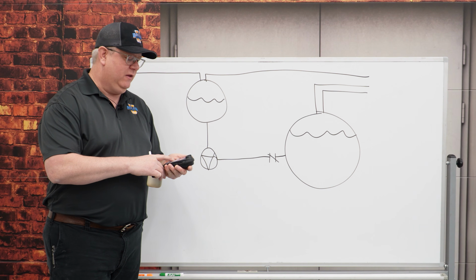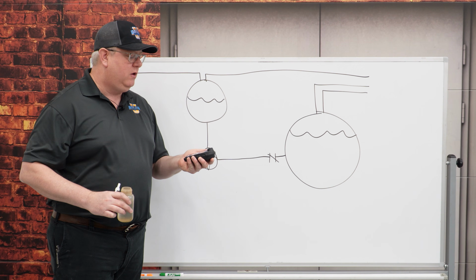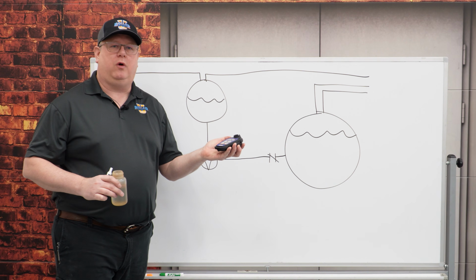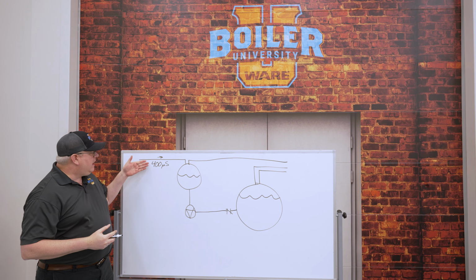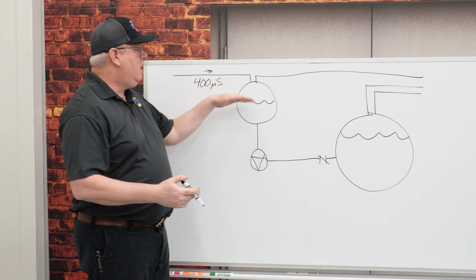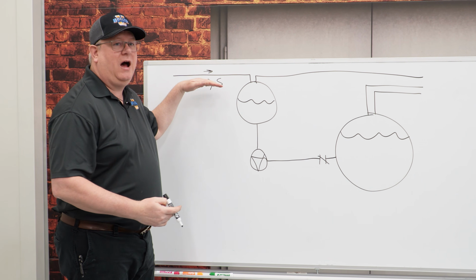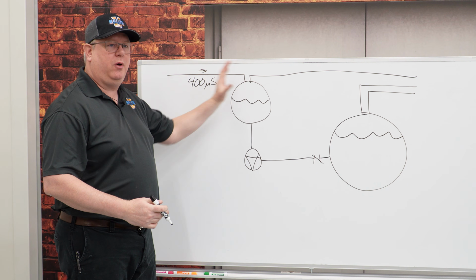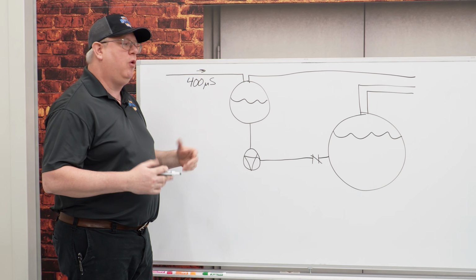And so if I read this freshwater sample out of our softener, conductivity is about 400. So if we've got incoming water to our system at 400 microsiemens, our feed tank is not going to be lower than that if we've got 100% makeup on our water. We'll get a little bit more into that.